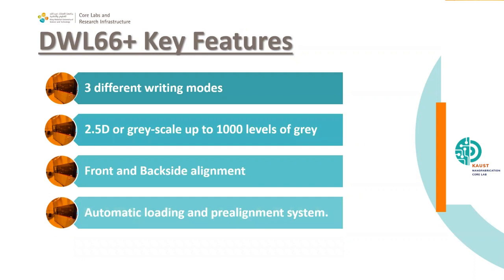And the last thing I already spoke about is the automatic loading and pre-alignment system, because this capability will allow us to program some exposures. Imagine you need to print 4 photomasks and you just program the tool to work during the night, and in the morning you will have 4 photomasks completely exposed, masks or wafers. I have to say that the automatic loading is limited, of course, to masks or wafers. It cannot be done for small samples. Small samples need to be loaded manually.